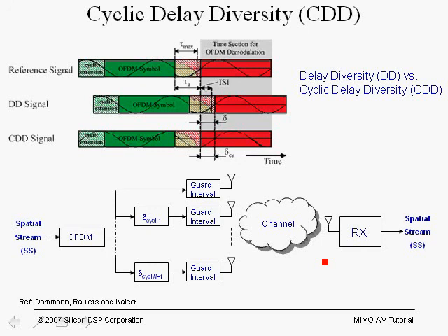And of course, as we'll point out later, once the preamble is processed and the signal field has been detected, then the legacy systems will be spoofed into not transmitting during the processing that is required for the 11n MIMO packets. So we'll get into that much later.